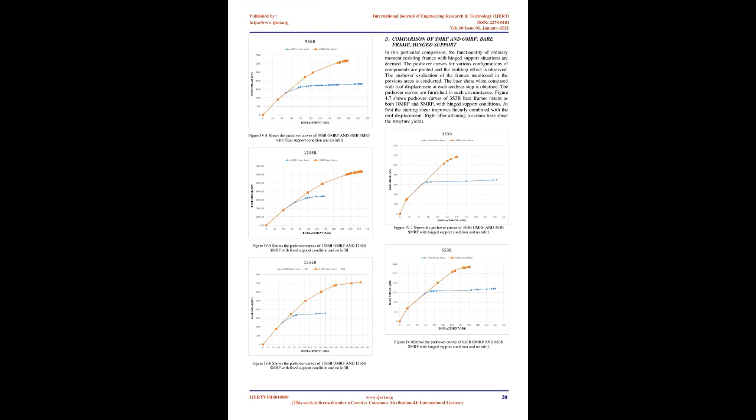For common building structures, it also provides an estimate of the global strength and stiffness in terms of displacement and force of the building structure. A typical design frame and a regular pushover curve diagram is shown in Fig 3.2 below. Typical pushover curve.